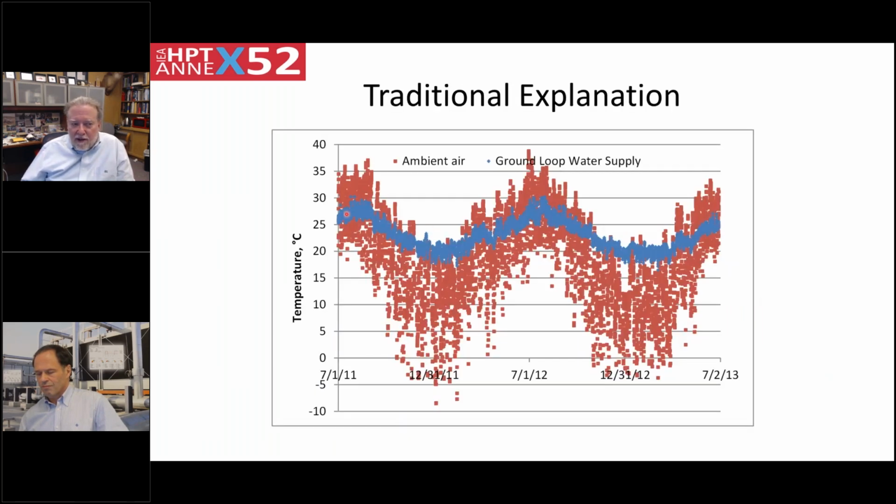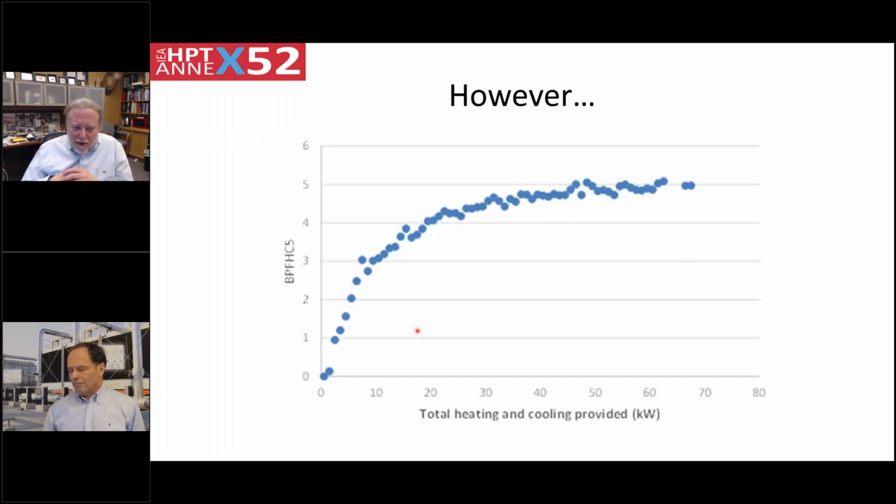explanation for this is that the ground source heat pump has better, more favorable entering temperatures. So when it's hot outside in the summer, the ground source heat pumps are getting temperatures around 26, 27 degrees C, whereas the air source might be getting 30 or 32 or even 36. Whereas in the winter, right, we have relatively warm fluid coming back from the ground, but cold air outside. So thermodynamically, that should be better. So that's one explanation, but it doesn't really tell the whole story.